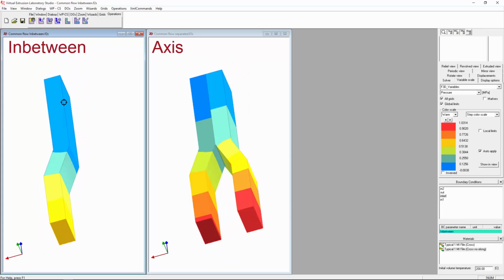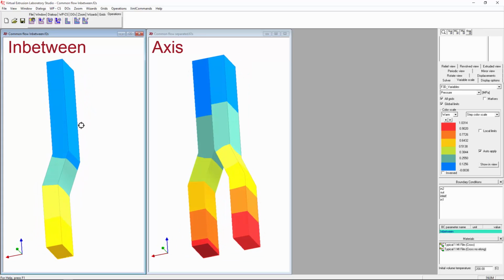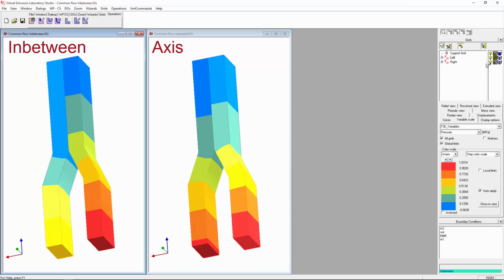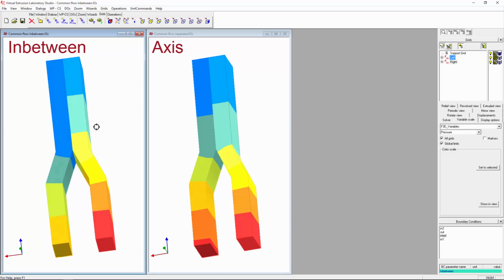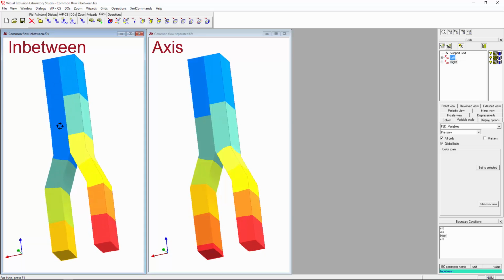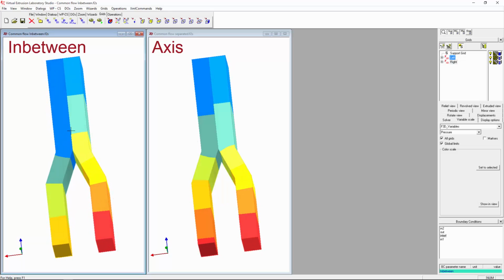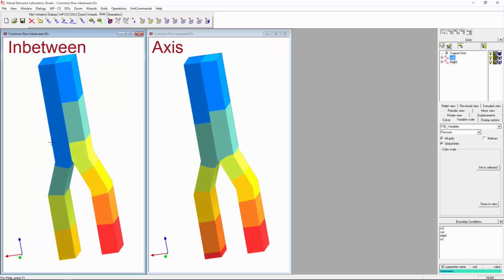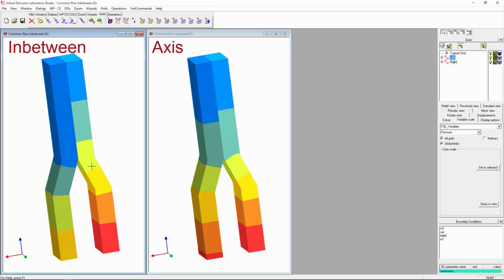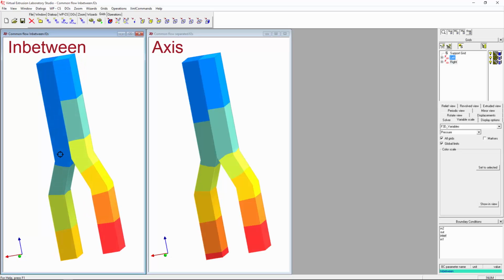What it does, basically, it says that the velocities will be matching, the degrees of freedom for velocity and also temperature will be matching. So that means that if you multi-select these two geometries, and if you solve them together, they will influence themselves. The problem is that the pressure does not, right? The pressure degrees of freedom are not depending on each other, so there is a discontinuity in pressure on the interface. So it is probably closer to reality because we see some velocities influencing, but we still don't have any flow across that boundary, okay?